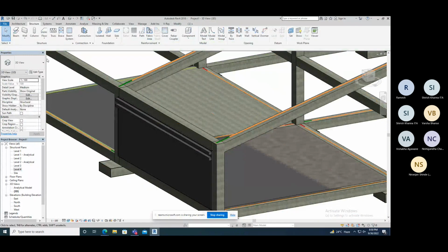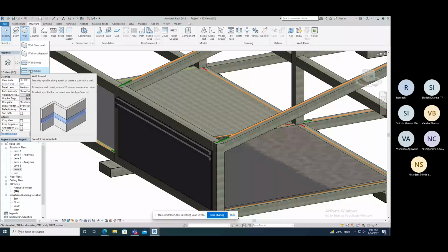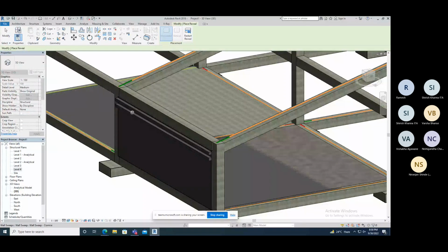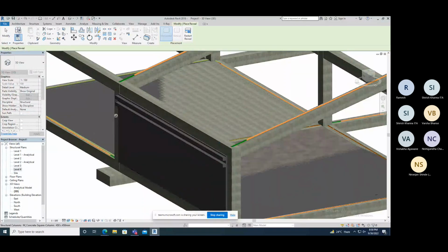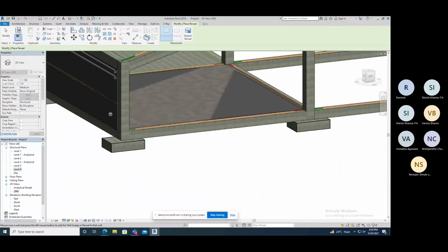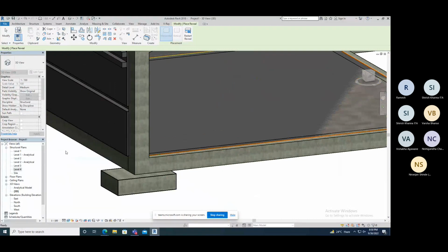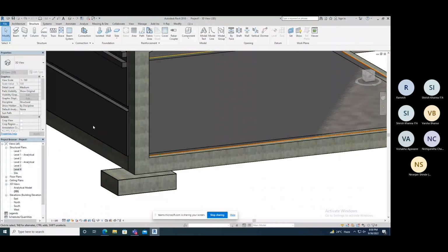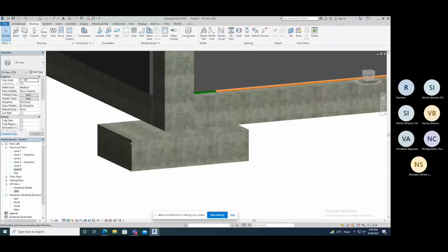Then we have some other options. One is reveal, the extruded one. This is a cut in the wall. See, in the image here, the portion you want to cut into a 3D wall, you can use this cut. See, it is there, inside. You can change the color so you can see properly. Now the cut is visible. Yes, that is the reveal.